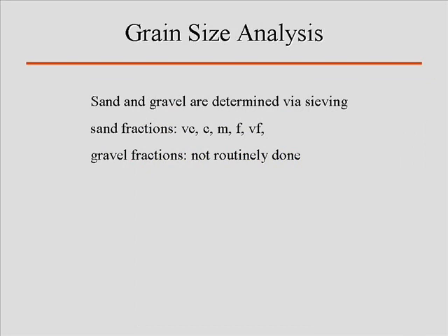All right? Now, in order to make this work, you have to have a fixed volume of water within the columns. That's 1,000 milliliters. You also have to know the starting weight of your sample. That's the first thing you do before you even start processing things. You've got to be able to take those sediment samples after they've been weighed and break them up to the finest clay and sand particles that are in there without literally grinding them up.